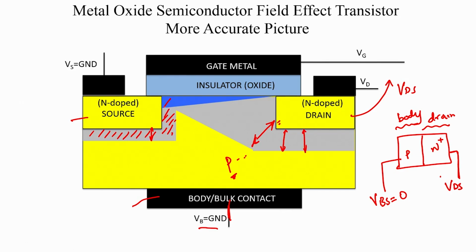And we also saw that the channel potential varies as you go from drain to source, and this channel potential also affects the free carrier concentration, which is the inversion layer charge, and therefore, one would find that the inversion layer charge actually decreases as one heads towards the drain side, and this leads to the pinch off and therefore your saturation mode characteristics. So, in our models so far, we never took into account this variation in the depletion layer thickness. And why is that important?